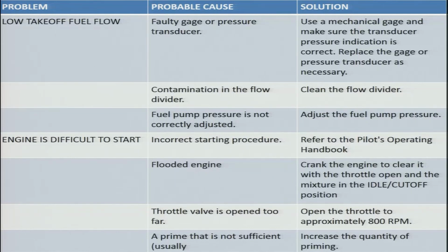Now, another problem might be that during takeoff we have low fuel flow. In case the fuel flow gauge is reading low during takeoff, what might be the reason? Again, the gauge might be faulty or the pressure transducer might be faulty. In that case, again we need to replace as required. Another reason might be that the flow divider has contamination in it. We need to clean the flow divider. Fuel pump pressure is not correctly adjusted, and in that case fuel pump pressure has to be adjusted.